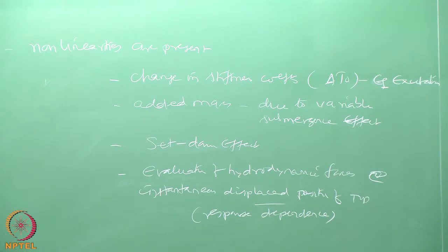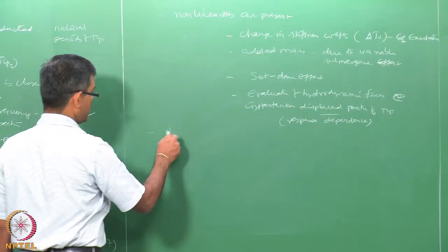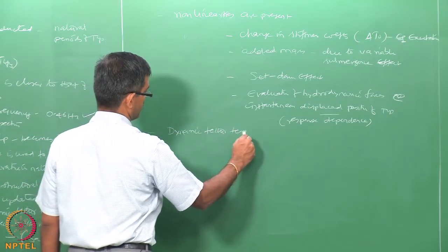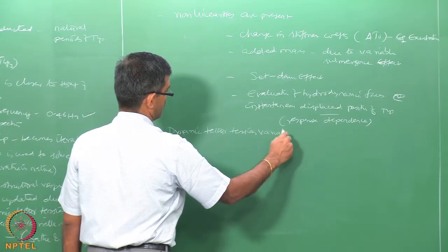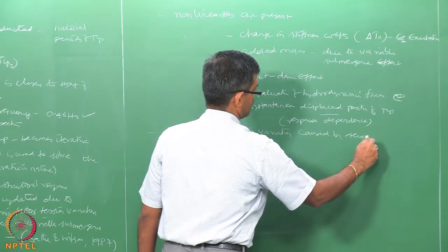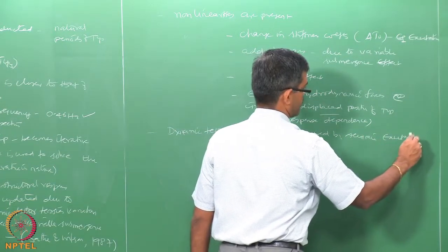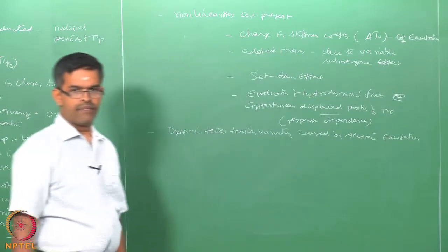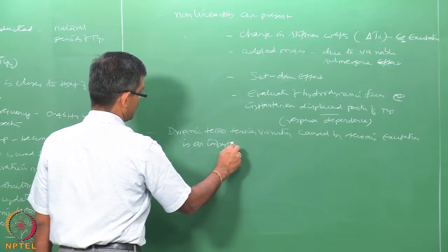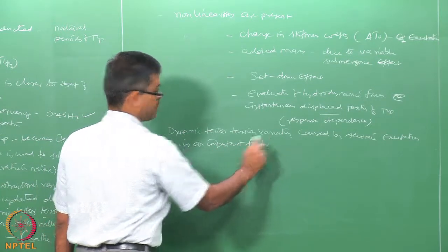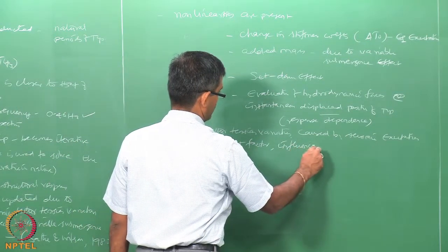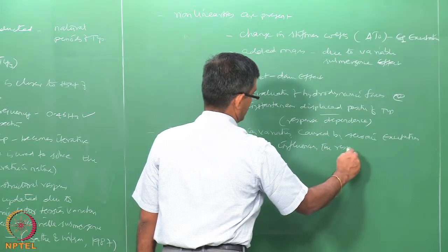So, one can easily understand here that the dynamic tether tension variation caused by the seismic excitation is an important factor influencing the response of TLP.